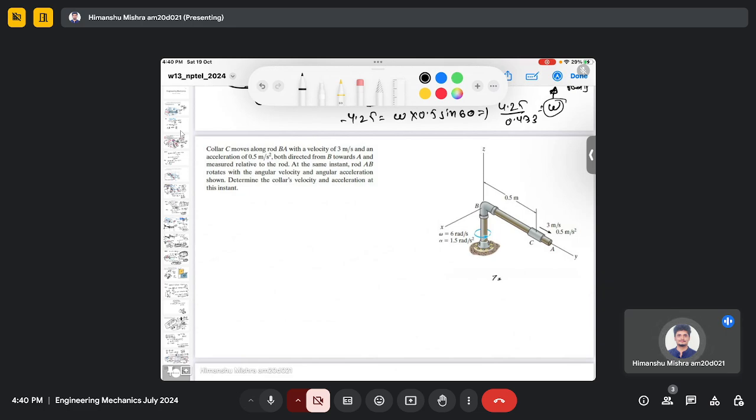in this problem. So you can see there is a fixed frame along this axis. If you define this axis as capital Z, then along this axis this can be treated as a fixed frame. But now if you need to find the velocity of this collar, let's say C, and if this AB is rotating, then you can imagine that the concept that you need to use in this problem is of rotating coordinate system or the moving coordinate system.